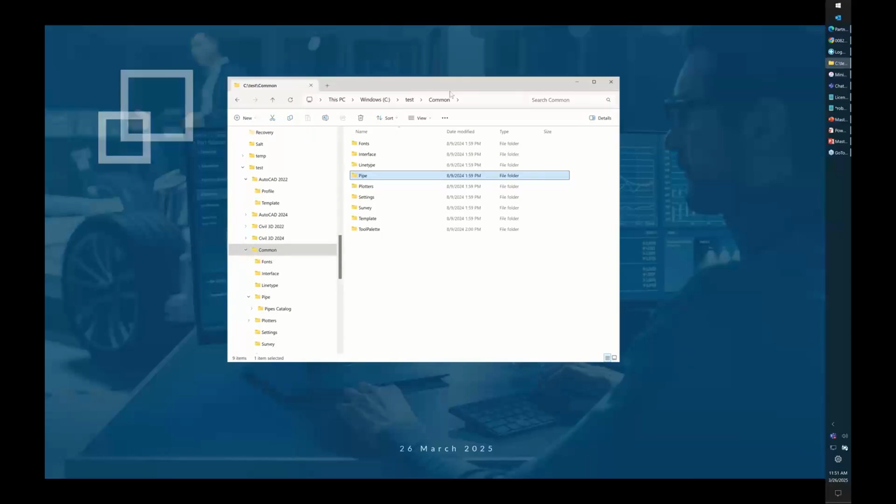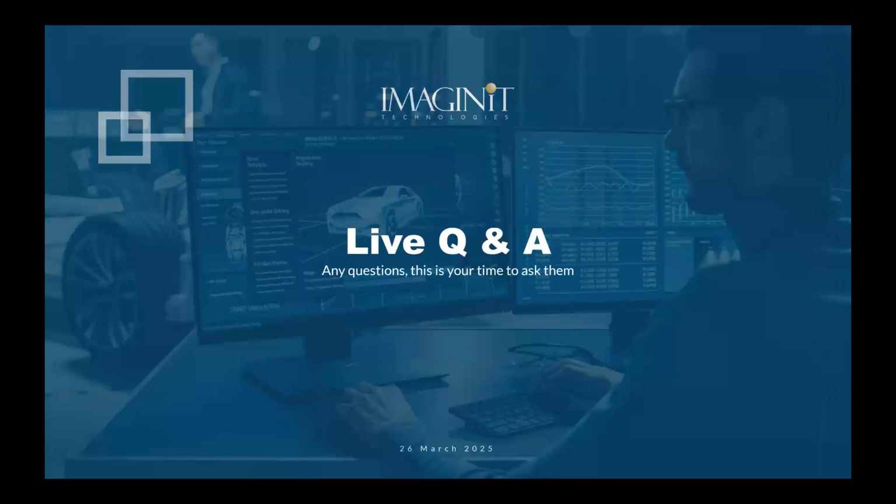Now, data references, things like that. If I'm in a project, I like to keep my data reference folder as close to the root of the project as I can. I have seen instances where people create all of their projects based off of a year in a drive letter. I prefer to segregate my projects for data shortcuts into the project folder itself and not linked to just a single drive. Let's see, that's more or less my preferred configuration.